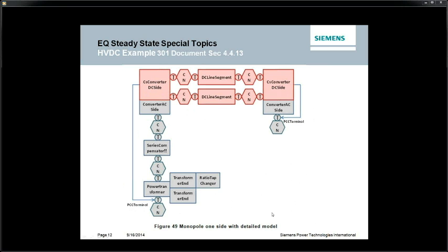So if you have some applications that are using the equipment profile, they may only be interested in steady state data, and that data is contained in that equipment model. And for those applications that are used in short circuit, they can use that same equipment file, and we can pass in the additional data specified by the short circuit profile, kind of overlay the existing equipment data. So you can add in your zero sequence, your negative sequence, and even if you'd like to, you could replace your positive sequence points if necessary.